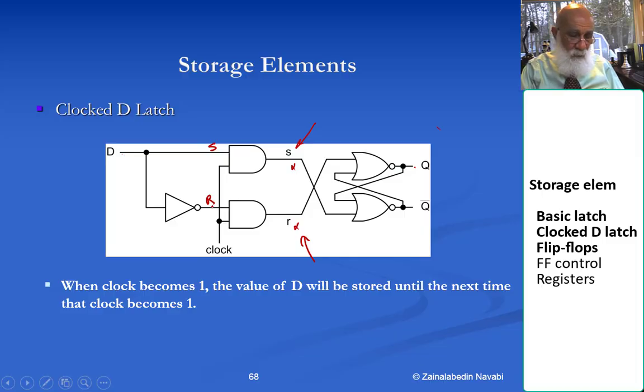Okay? For now, don't look at the structure on the left hand side. So it's saying that I only allow capital S and capital R to reach lowercase s and r only when there is a pulse on the clock. And therefore, I'm controlling the timing of this circuit. The timing of the circuit is controlled by pulses on the clock.